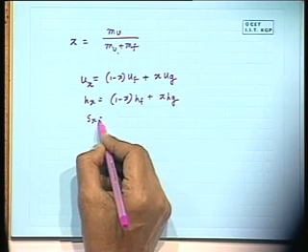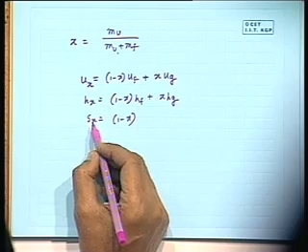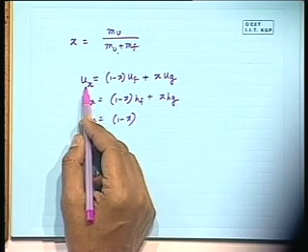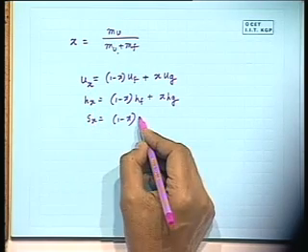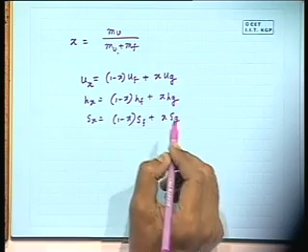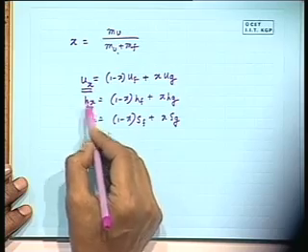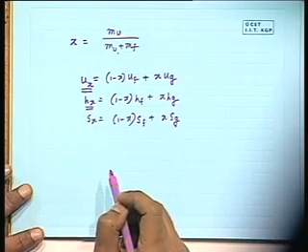Similarly S, that means all intensive properties corresponding to the extensive properties, that is specific internal energy, specific enthalpy, specific entropy. If I know the values of these properties at the two saturated state points of the two phases, then I can find out the values for a mixture of these two specified by X.